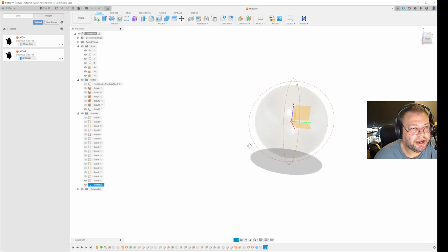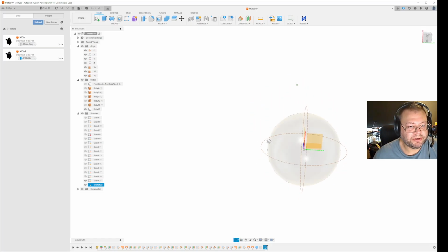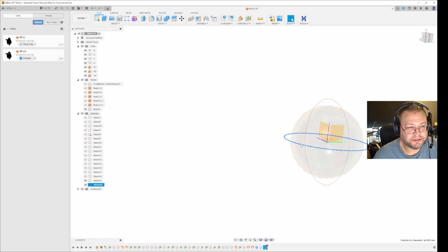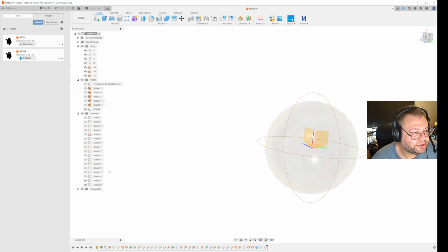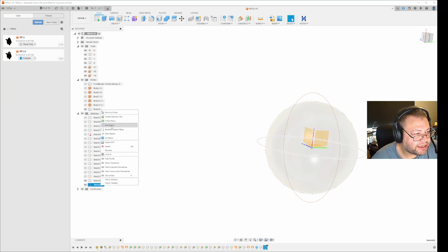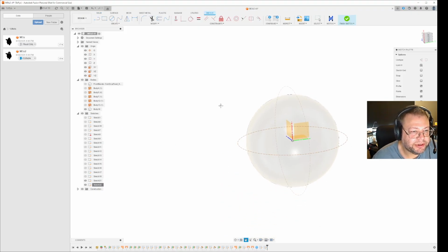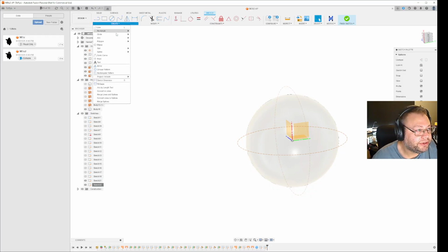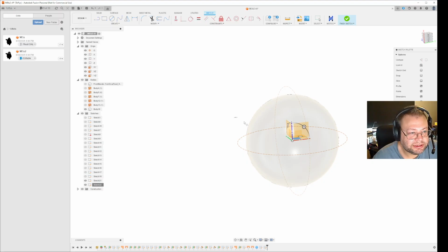Now, I always thought that if I wanted something upwards from here and into space and raise vertically, I had to make construction planes and then put points by using a pattern around. But actually it's much easier than that. Now, let's say I just want to add a point on any of those axes, I edit the sketch, I go in and create a point, and I can just put the point there. Make sure you are in 3D mode for this.